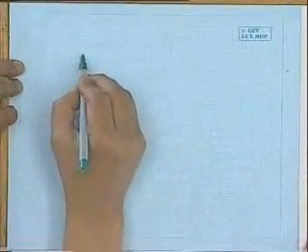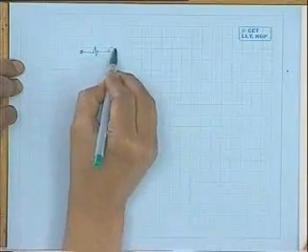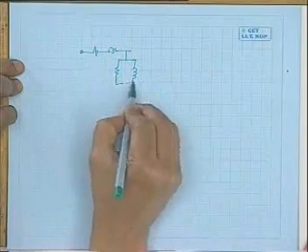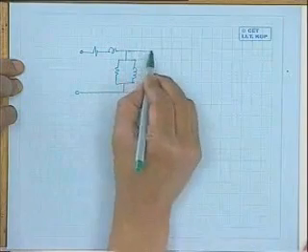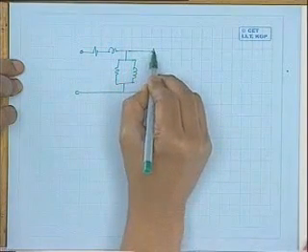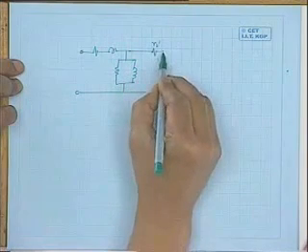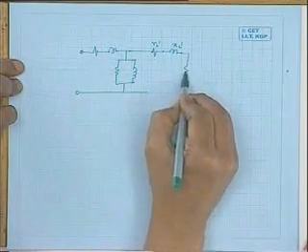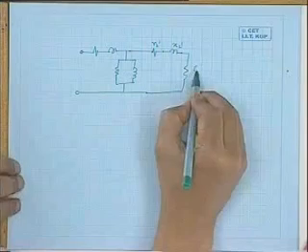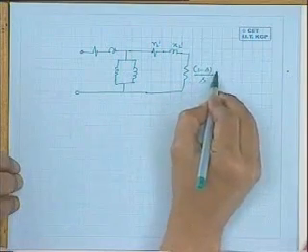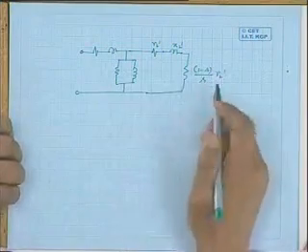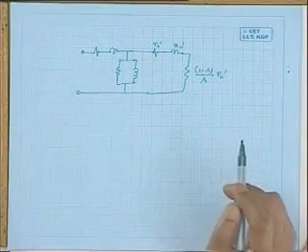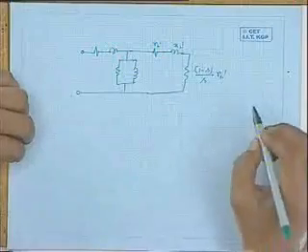It is precisely for this reason that this resistance is often shown divided into 2 parts in the rotor circuit. You draw this one, and here you can show it like this. This is the rotor actual resistance R2 dashed, then your leakage reactance X2 dashed. Then, because these are all in series, you show (1 minus S) by S into R2 dashed, and the power in this resistance will represent the mechanical power developed in the machine.